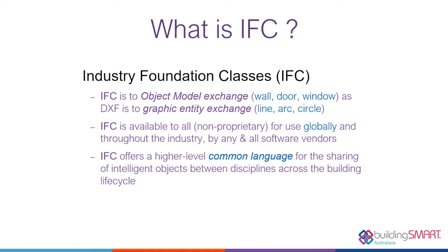Now, if you're authoring BIM models, then you would author and save files to formats like .rvt for Revit, and they have a database format for concepts like walls, doors, windows, etc. IFC is a similar concept to that, where it has lots of concepts around the built environment. So it also has concepts and relationships for walls and various other things through all stages of a built environment project. So from concept to design through to construction, handover, operations and maintenance, and even through to demolition.